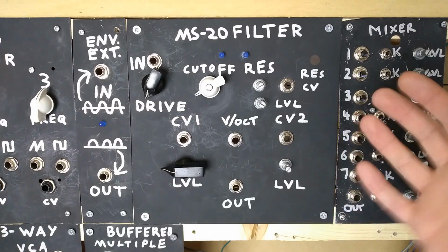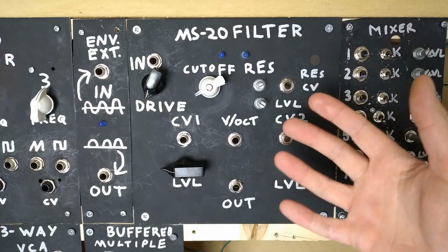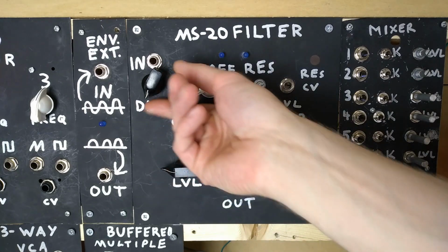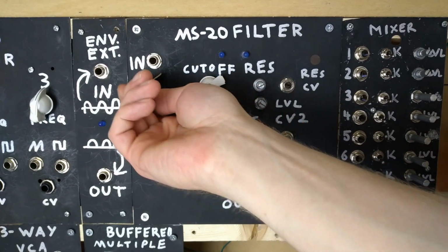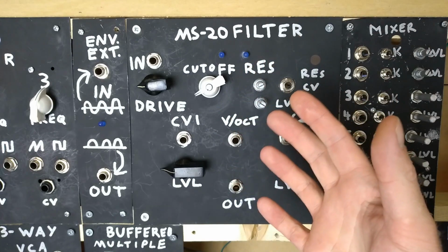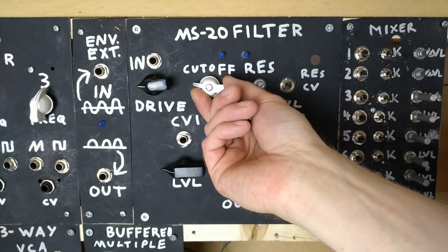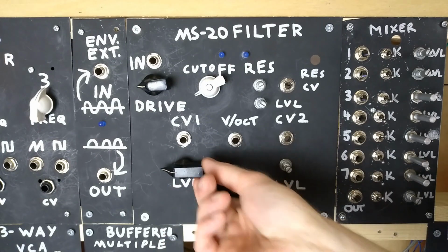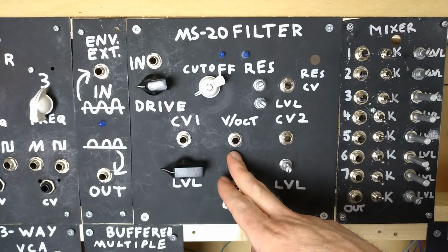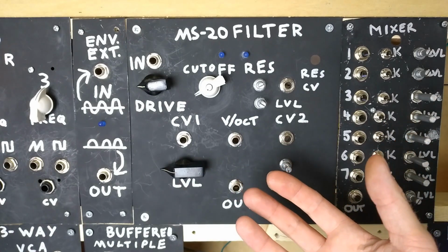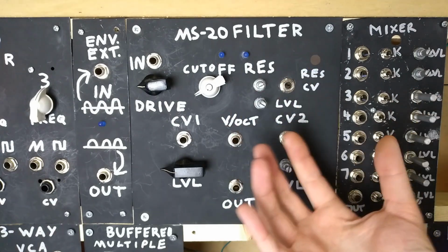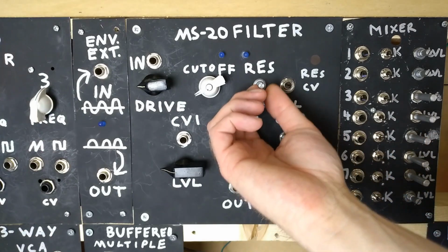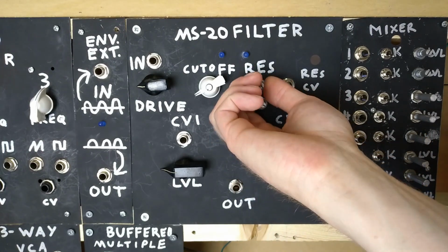So to demonstrate a filter with resonance, this is where the MS-20 filter finally comes in. So let's take a quick look at what we have here. We have our input with a drive control where we can crank the signal a little bit, which is a feature that I added to the original circuit. The cutoff, where we can adjust the cutoff frequency, which also has 3 CV controls over it. 2 with dedicated level controls, and 1 direct volt per octave input, where we can technically plug in a keyboard and play the filter when we crank the resonance, which leads me to the resonance control, where we can adjust how close to self-oscillation, or even fully into self-oscillation, we can push the filter.